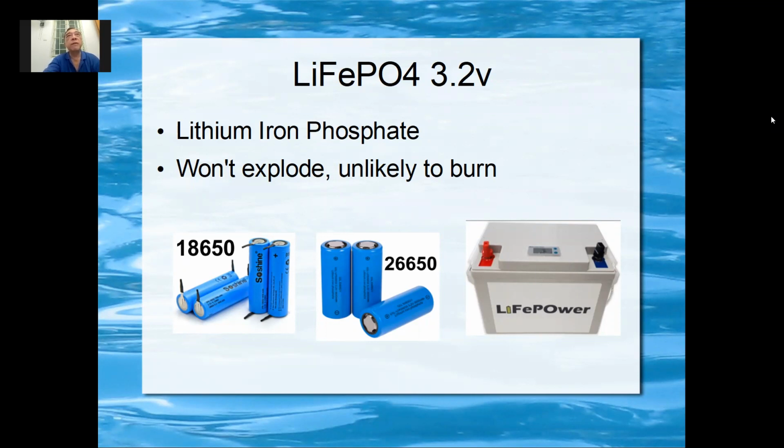But for lithium battery, because they have electronics inside. Okay, when you look at this battery, it looks just like an ordinary battery, but inside there's electronics. So when it is fully charged, it will cut off its own circuit. So it will not let you charge anymore. Because if you continue to charge, you will damage the battery. So when it's fully charged, it cuts off.